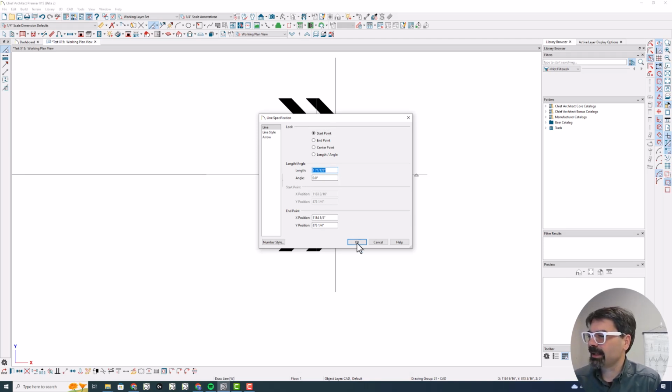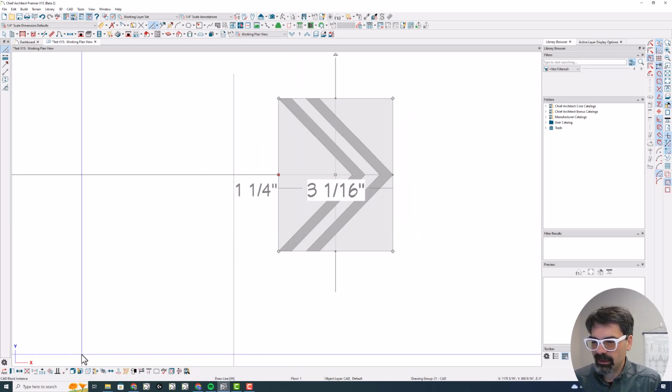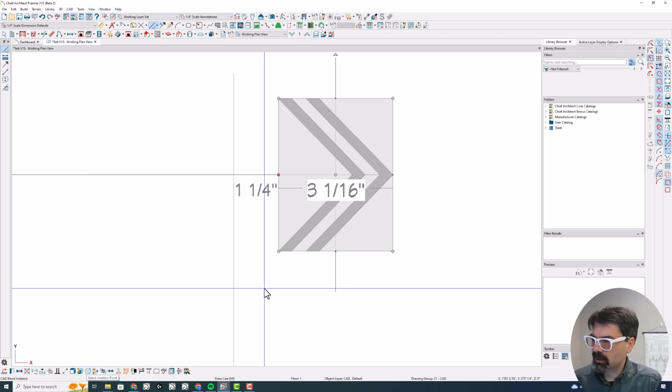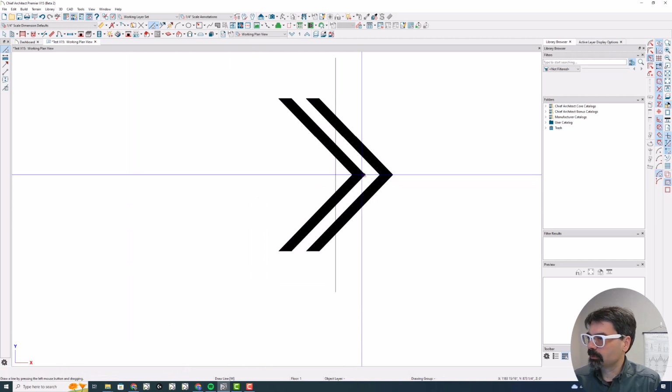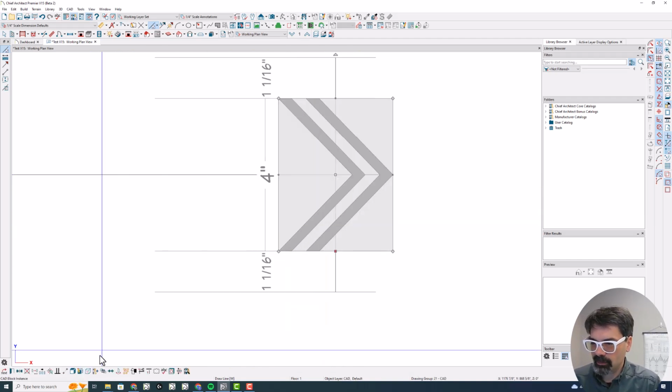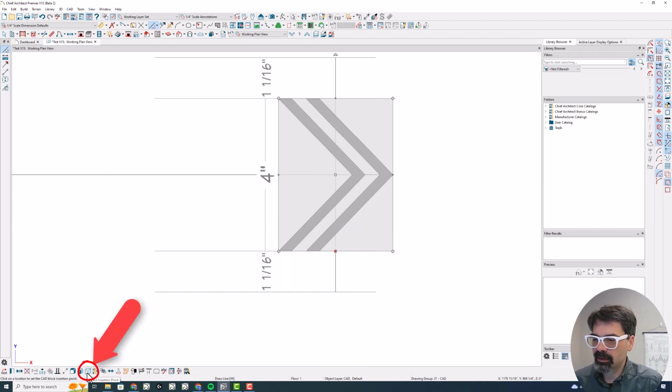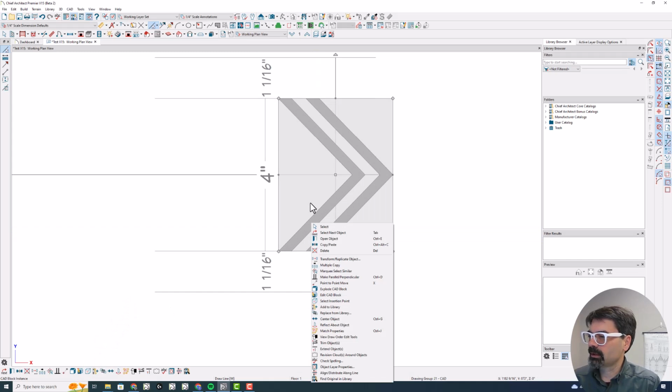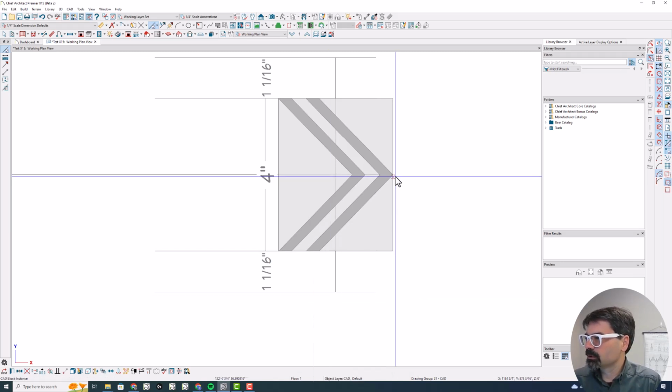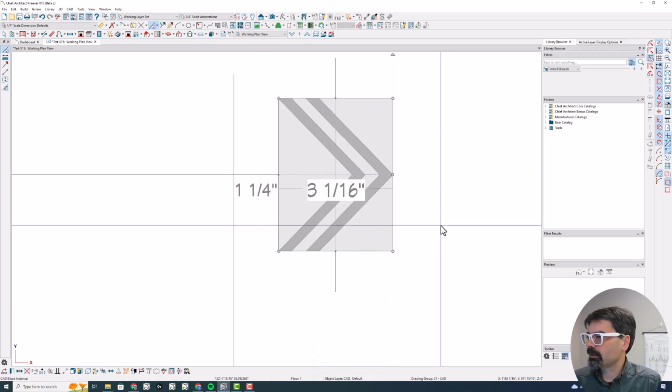And so I'm going to copy that and open my CAD block. There we go. Let's select the CAD block. I don't have to do the measurement part. Let's just select the CAD block and click this plus here down in the edit tools. Edit insertion point. Or if I double right click on this, my settings are to double right click to pull this up. Your settings, you might only have to single right click. Edit, select insertion point, and we're just going to click that spot right there. Okay.